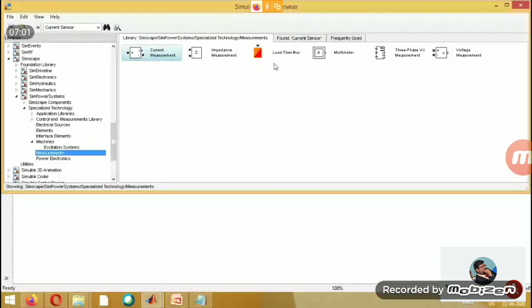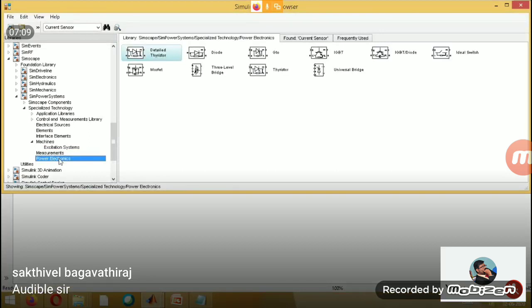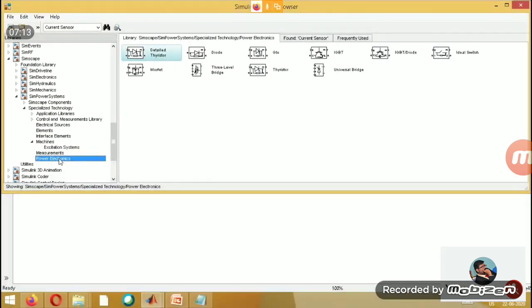Okay. So we have seen till measurements. There is a V measurement block and an I measurement block. And then moving to the next section, which is power electronic devices. We all know there are so many types of devices like MOSFET, IGBT. We preferably go for either MOSFETs or IGBT because they are high voltage and high current devices which are voltage controlled. So whenever you want you can turn on and turn off. There is some difficulty with current control devices.